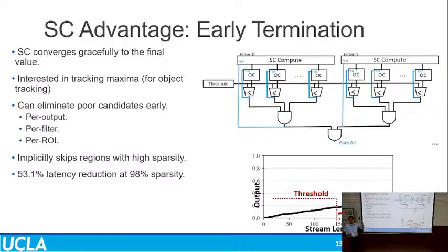But leveraging, knowing where the zeros are, and compressing the compute is very, very hard for conventional digital accelerators. That's why if you look at sparse matrix multiplication algorithms, the point at which they're actually faster than dense matrix multiplication is when the sparsity is upwards of 99 point something percent. Because the effort required to detect where the zeros are is more than just doing the operation itself.